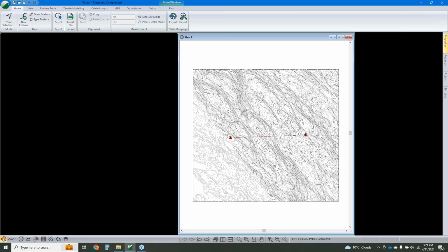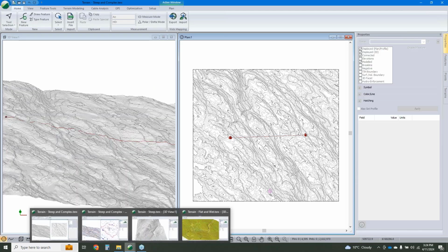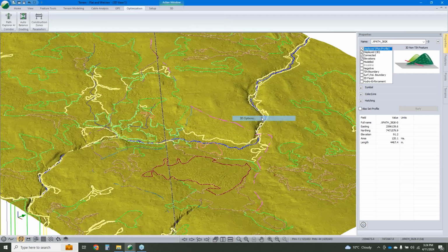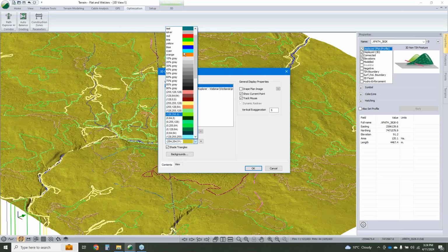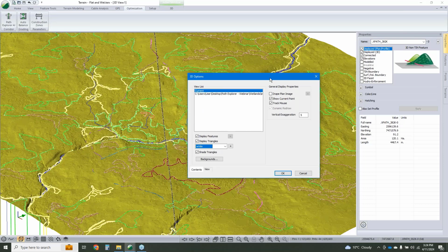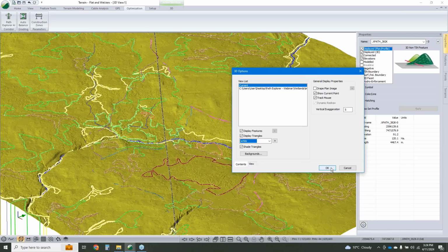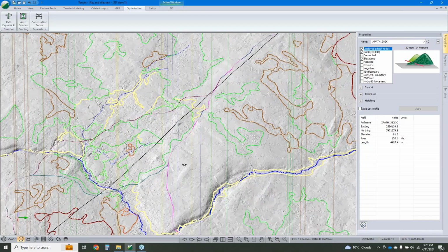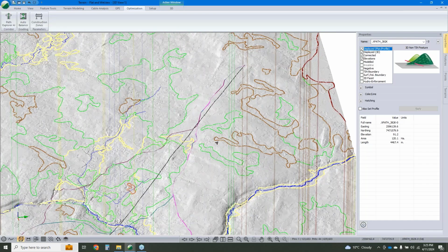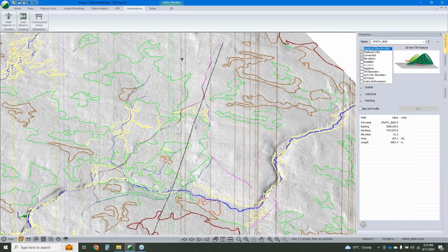And while you're in that one, Matt, I just wanted to highlight too, if you're wanting to see your full Path Explorer paths, our terrain surfaces in 3D are typically fully opaque. So if you want to see what the path looks like, you can just go in and set an alpha channel to control that visibility. So it doesn't look like a broken up road. Yeah. So here it's under the surface. We've changed that. I'm also going to change that mustard color to be something a little easier to see. And there we are. And those lines that are extending off, I've just got some draped features that go off my surface. So yeah, totally can see through there.